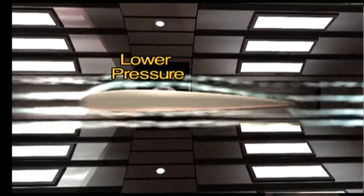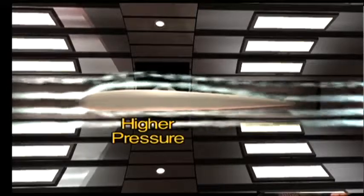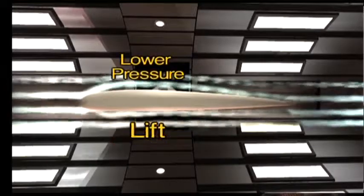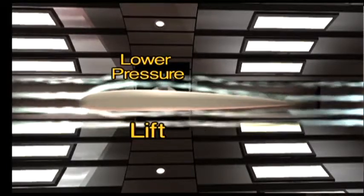Under the wing's bottom surface, air molecules do not have to travel as far. Now, these molecules don't accelerate as much, and therefore the air pressure is greater than that over the wing's upper surface. The product of this differential pressure is called lift. This lift production is a function of camber and airspeed. Lift increases exponentially with airspeed. For example, doubling the airspeed increases lift, but not linearly, exponentially.